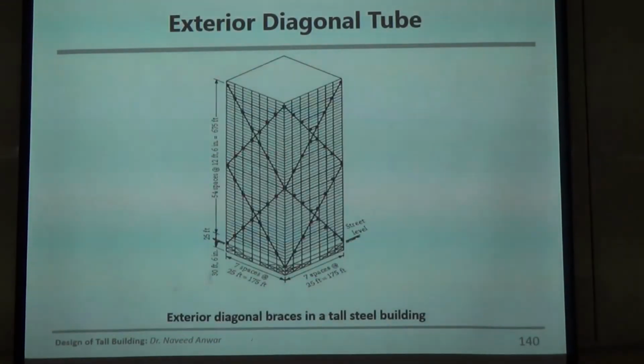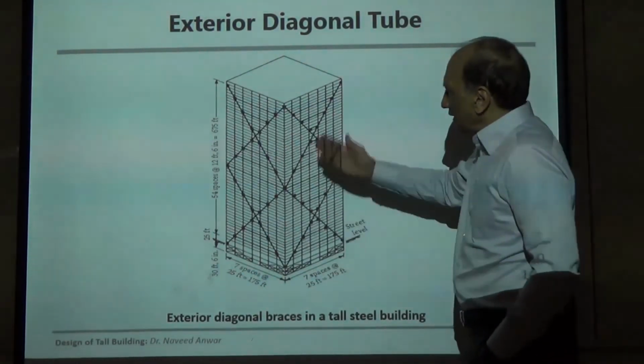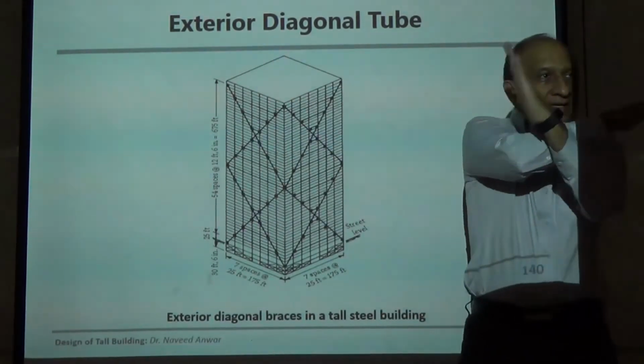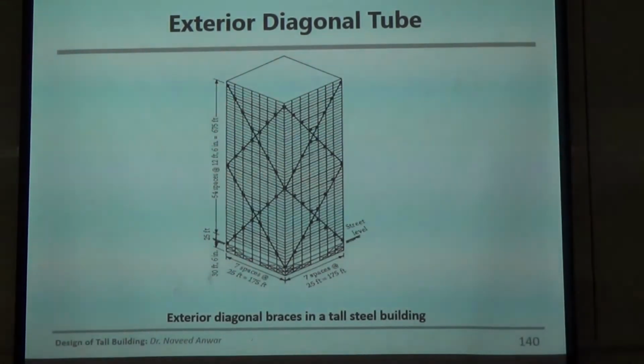And sometimes, as I mentioned to you last time, to reduce the shear lag you can put diagonal bracing into the building to reduce the effect of the shear lag. You can put big diagonals and they will act as a truss. So this will be a complicated system having a tubular behavior, local frame behavior and a global truss behavior. You can see engineers have been very innovative. Your seniors have always come up with very good solutions whenever they face a challenge.